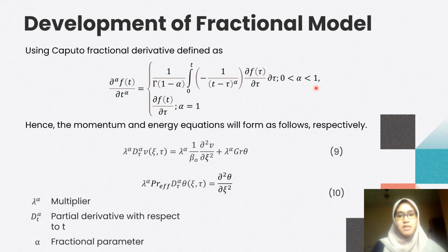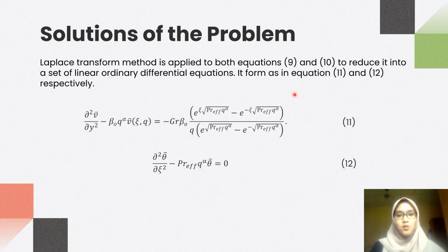After the non-dimensionalization process, the equations are converted into time fractional form using the Caputo fractional derivative. It is worthwhile to mention that fractional models are more general and convenient in describing flow behavior. Furthermore, the fractional model's result is more realistic because the obtained results can be compared to experimental data for excellent agreement by adjusting the fractional parameter. The solutions are obtained by applying the Laplace transform method.